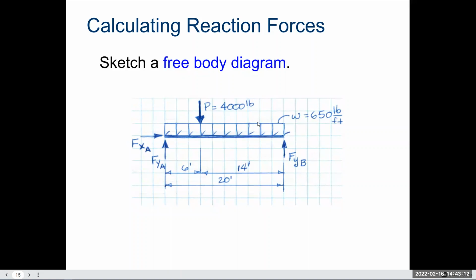All right, next up, free body diagram. You've probably heard this term if you've done a physics class. Really, a free body diagram is isolating all the forces. In this case, we see that our reactionary forces, Fy at A, Fy at B, those are the forces going up. And then since this side was a pin, technically it has a force X coming across.